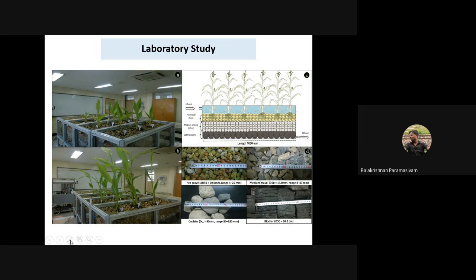So this is what I was telling you. We can use biochar in the constructed wetland system. It will improve the treatment process, filtration, and biological degradation. That is the one modification we can provide, biochar. So P gravel, medium gravel, then pebbles, and biochar. If you see the arrangement, the top and bottom layers are medium gravel and P gravel, and in just one, we are providing pebbles.